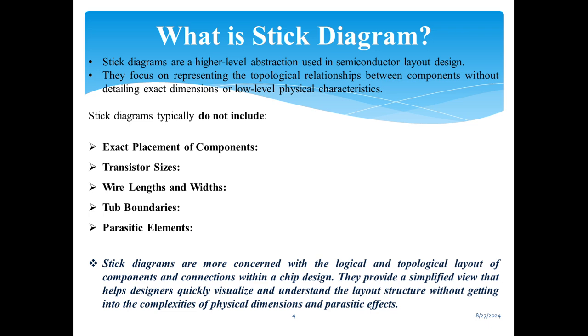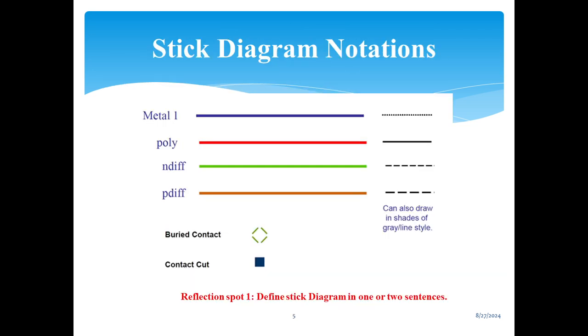layout. Stick diagrams are more concerned with the logical and topological layout of components and connections within a chip design. They provide a simplified view that helps designers quickly visualize and understand the layout structure without getting into the complexities of physical dimensions and parasitic effects.